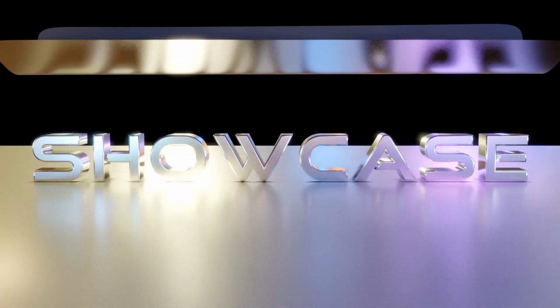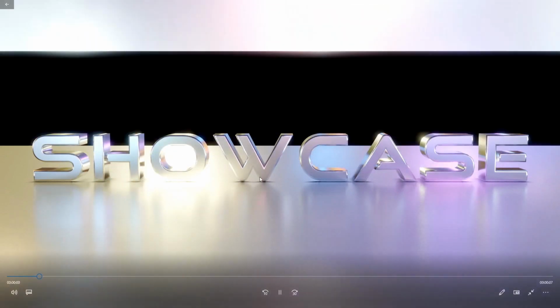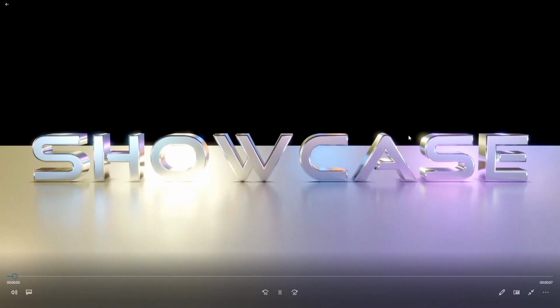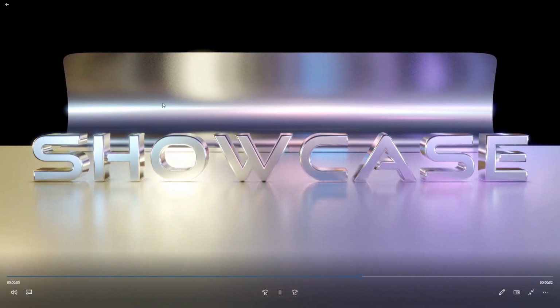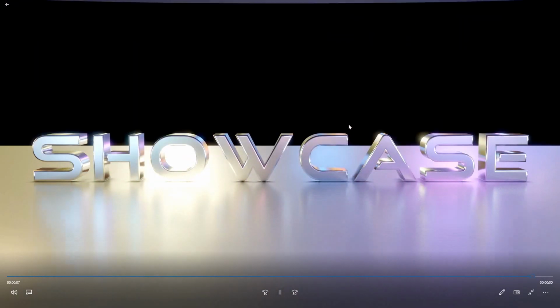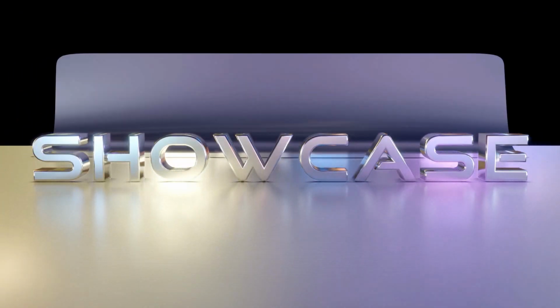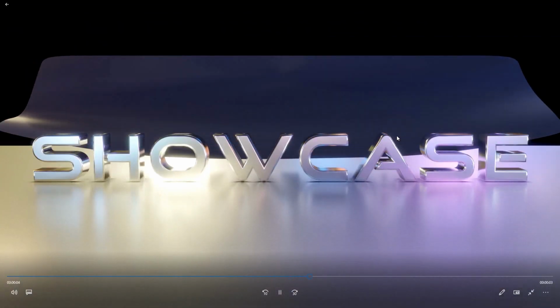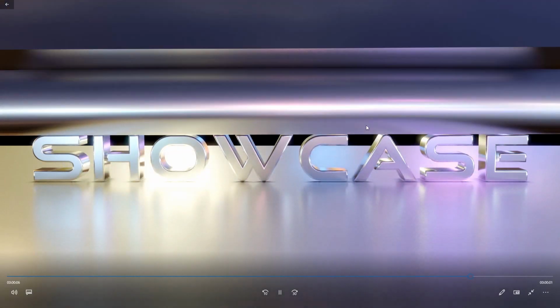I think we could have improved this, but overall I'm quite happy with how it's worked out. I think at the end we could have had the cloth flow over the text a bit better. We pulled it quite fast, right? Imagine the cloth is behaving in a certain way, and when we pulled it back, it was more frames, and then on the pull forward, it was less frames. So it's pulling it quite fast, so it didn't really flow over the text as I would have liked. But the idea here was to learn how to use the cloth simulation in Blender, so now you can go and experiment. Maybe slow down that pullback on the frames.